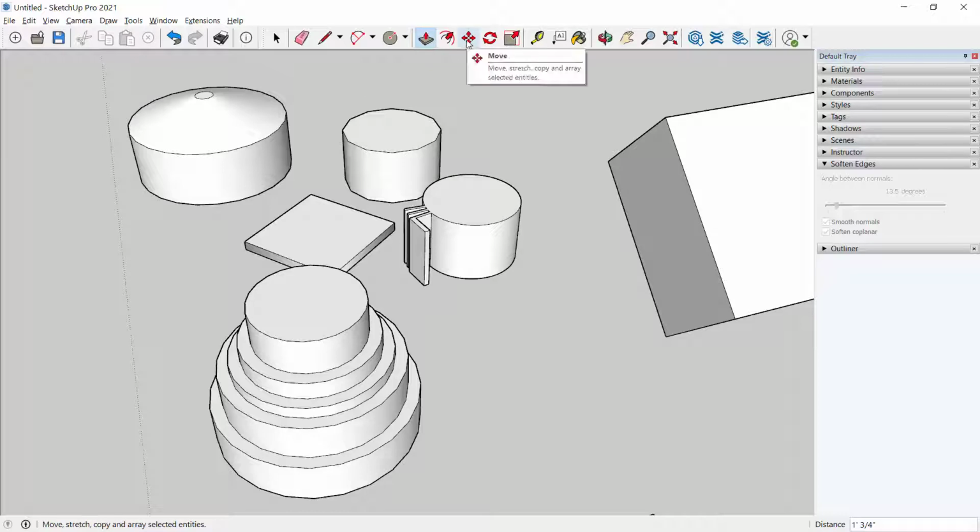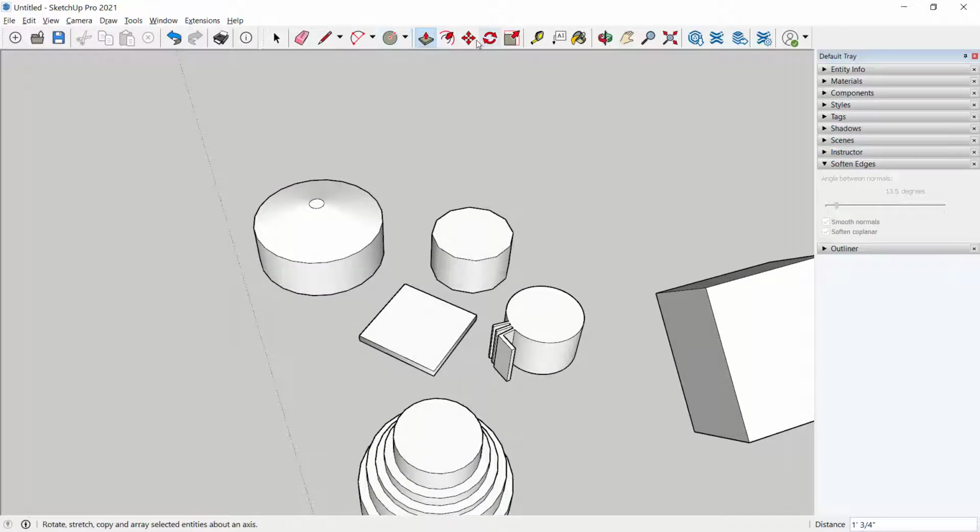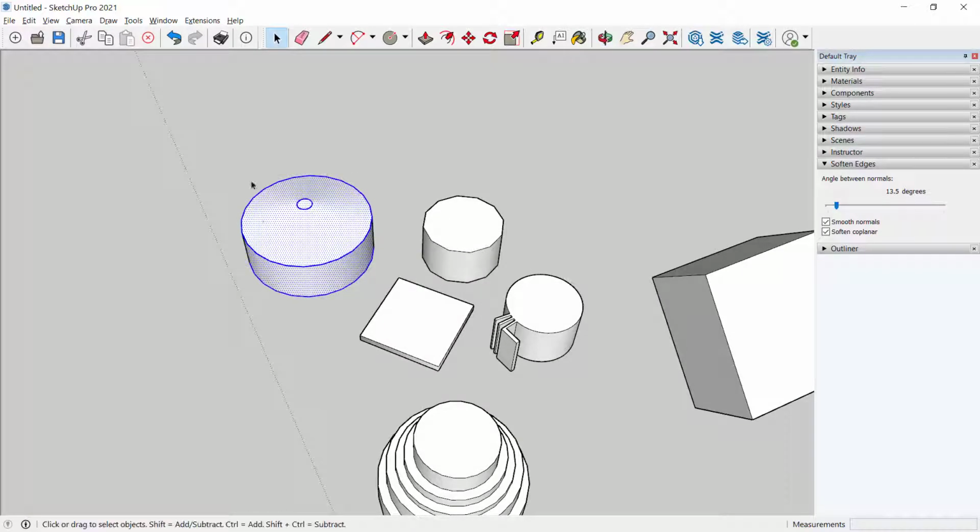The Move tool is actually probably the most handy tool out there. And Move, one of the advantages is that any object that is selected, this is where you can both move it dimensionally but also make copies. So let me select an object. By the way, to activate the selection command, just tap the space bar. And you might say, how do I know how to get all these keyboard shortcuts? Well, let me show you.